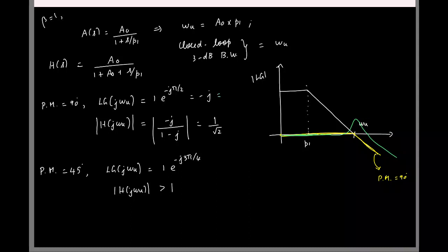Loop gain is basically, the phase margin is 180. This will be minus 1. Right? Phase margin is 0 degree means the phase added is minus 180. Minus 1, so loop gain by 1 plus loop gain, it will blow to infinity. So you will basically have something like this, right? I'll probably quickly write it. So this is for a phase margin of 0. Okay. Again, this kind of peaking is something you don't want in your system finally, right?